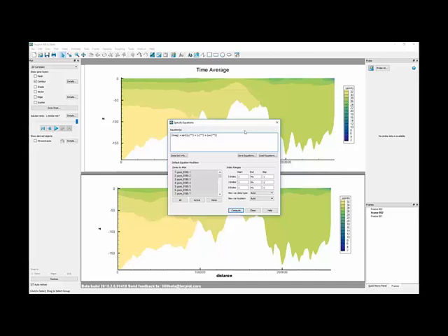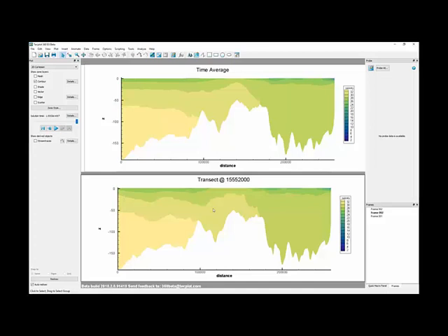All right, and that's all there is to it to compute a new variable. Curly braces being the big thing you need to know here. We have a lot of built-in functions, square roots, cosines, etc., and those are all available in the Help menu. So here we can just hit Compute, and now I've computed velocity magnitude for each one of these zones.